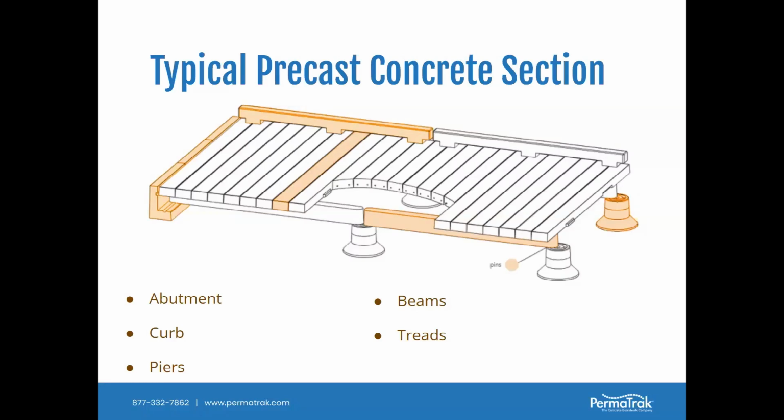Also in orange are the stringers, or what we call the beams. The beams would run from pier to pier, and with a concrete system, the strength inherently allows you to really expand those lengths. Instead of normally being limited to, say, a 10-foot span, a concrete system can certainly take you 20 feet and beyond. And we've even seen systems out of concrete made 30, 40, and even upwards of 50 feet in span length.